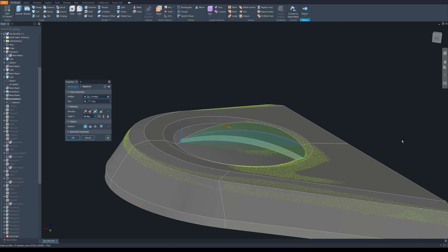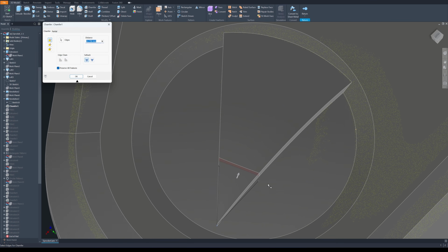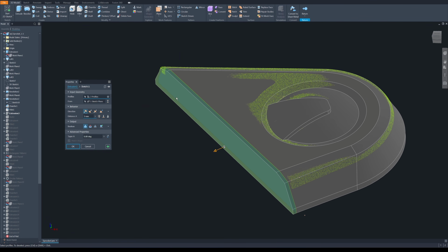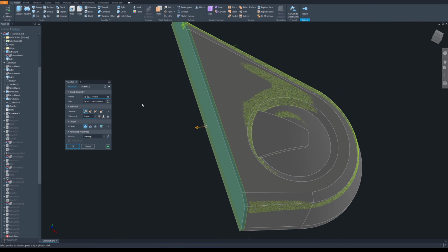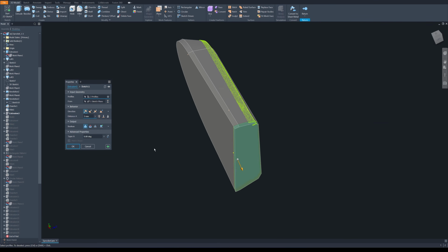Right, it looks like a pie. And next, I use a chamfer command to make a cut. And then I fillet the corner. Next step, I extrude here for about 3 millimeters longer because the first profile that I made was too short. So now we have a solid.